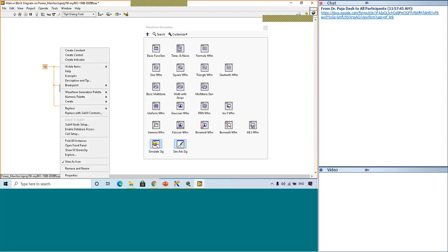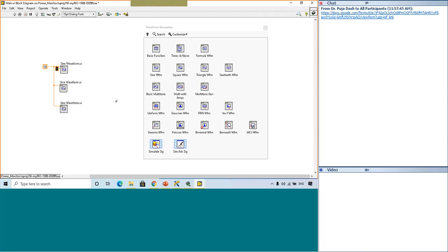And then the amplitude. I wish I could give 230, but 230 volts amplitude does not equal 230 volts RMS. If I measure it, it should come as 230 volts RMS. So if I give 230 here, it states that its maximum value and minimum value is just 230, and if you measure the RMS value there, it will not be 230.